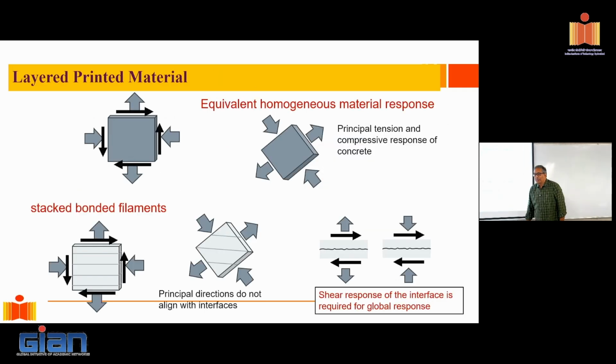Let's look at this. Suppose I look at a complex state of stress that I subject the concrete to. Now, how do we understand the behavior of concrete? Concrete doesn't understand shear. Concrete only understands compression and tension. So if you're given any complex stress state, first thing is to look at the principal stresses. Concrete behaves a certain way in tension, a certain way in compression, and it's a combination of these two that dictate the behavior of concrete, period.